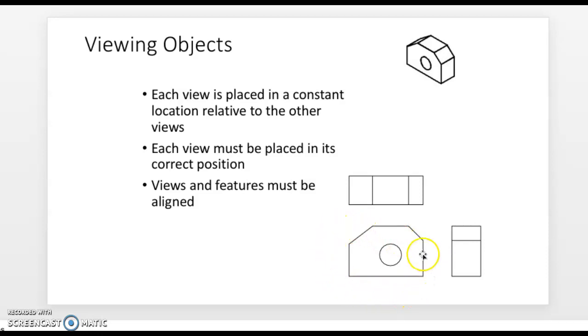Front view is always in the middle, typically in a lower left format. If you're looking at this on a template A, the top view is located directly above the front, and conversely, the right side view is always located to the right-hand side. Please notice on your screen that the left edge of the front view is aligned with the left edge of the top view.